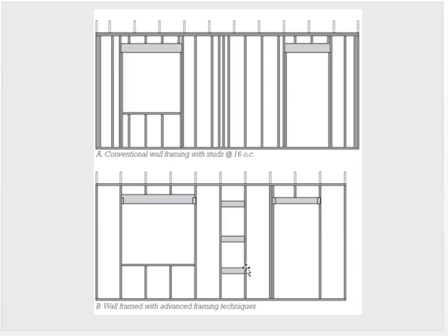But kind of the moral of the story for me is, if it were my house, I would not take out these second members. I don't think this is providing enough rigidity, enough nailing surface, so I would not do that. What I do like about this bottom one is that everything is laid out on that 16-inch increment.